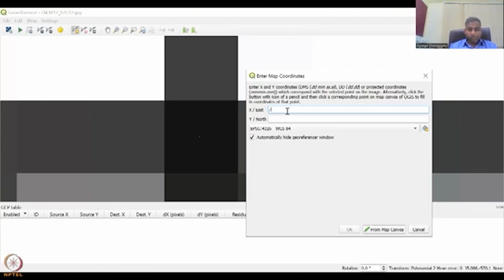So we're going to put 77, and this one is 35, so 35 space. Look at the format DD. So I put 77, 35, 5 is 35. Suppose you have 03, you have to put 03. Don't put just 3, it needs a value. Okay, so 35 and then a space, and then the seconds is 0, so you can just leave it because 35 is enough. And then on the bottom, this line, your latitude line is there.